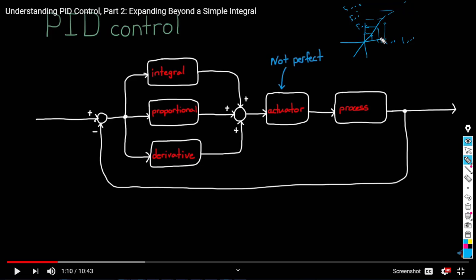This is a linear system. There is no problem. But in reality, your actuator has saturation, maybe from 0 to 12 volts, or from -5 to 5 volts. It has saturation, so it's not linear. If I apply 12 volts, okay, it's linear. But if I apply a high input, it doesn't keep going proportionally.